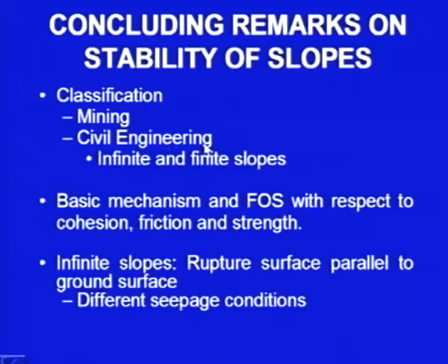In civil engineering slopes, we discussed infinite slopes and finite slopes. I started with the basic mechanism, where the mechanics is important: what the mechanics is and how it is used. We discussed the factor of safety with respect to cohesion, with respect to friction and strength.